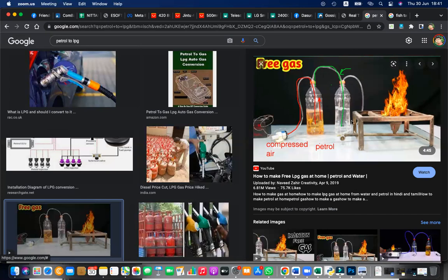There is another reason. Water pressure works as a seal. Therefore, petrol cannot evaporate by itself. Usually petrol can evaporate, but the water works as a seal and stops that. When pressure is given, the bubbles will be released and go through this pipe, and then you can make fire. So this is for safety as well as to stop evaporation when compressed air is not provided.